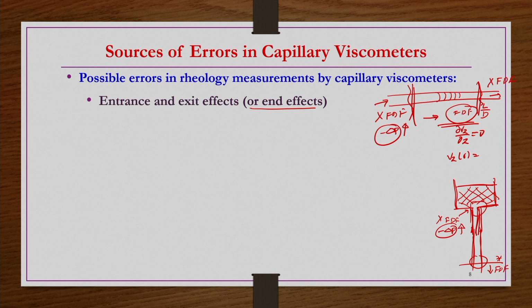How much it is increasing, we have to find out, and then from your true delta P you have to subtract that correction, the increased pressure drop at the entry level. So, let us say it is showing 15 Pascal, that is, at the entry level the pressure drop is 15 Pascal more than the average pressure drop in the fully developed region. Whatever delta P versus Q data you get, from the delta P you have to subtract this one. That is what we are going to see, right.